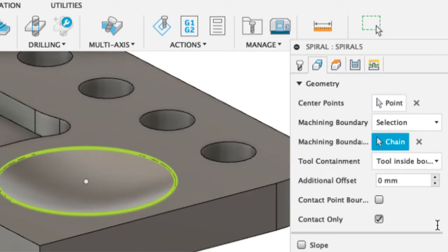So in the second tab here, go ahead and create a circle. There's the edge of it. And then you have to click it. And then instead of silhouette, selection, and then circle the edge. And then into the tool segment boundary, tool inside boundary. And then in the fourth tab, one more. Instead of going there, I just started outside in. Instead of 6.25 to step over, 1.